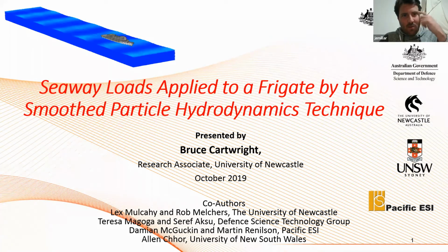Andrew Baglan, how many particles are in your model? I think that's part and parcel with the previous question. Yeah, it is, but it's a good question. The models like the one in the top left-hand corner of the title page would be used for the rigid body analysis, and we probably run about 600,000 particles in those. But as I mentioned, with the use of the supercomputer, with the speed increase and the time that we've got available, we're expecting to run certainly in the tens of millions of SPH particles.